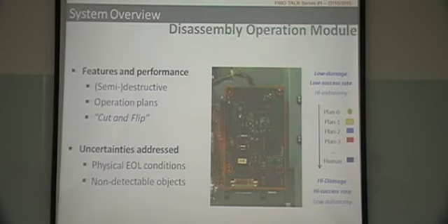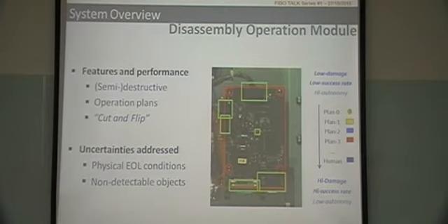So firstly, we can localize this one. We detect the circuit board, and then we just cut around. If it's cut around and all the screws are cut, this usually means you can detach it. The circuit board is normally fixed by four screws and some cables that are connected. So if you detach all the cables and unscrew it, you can remove it. Right? So if you try this and it's good, that's fine. But if it doesn't, what's going to happen?